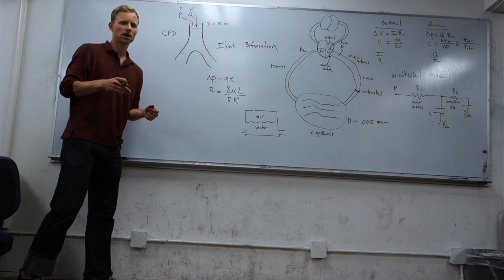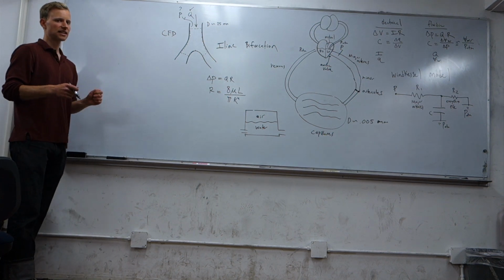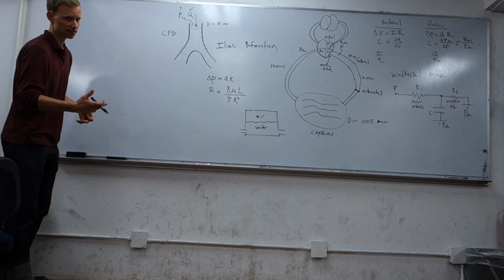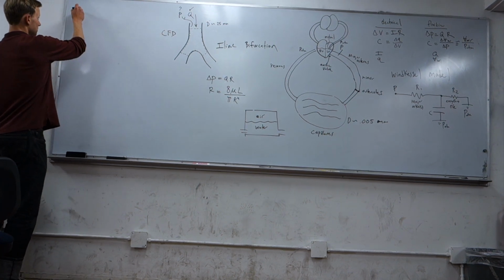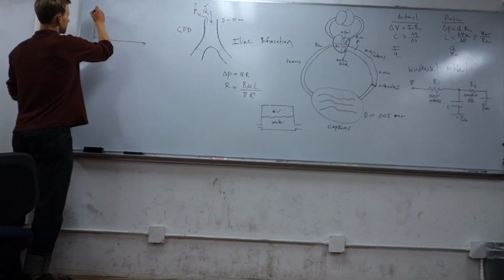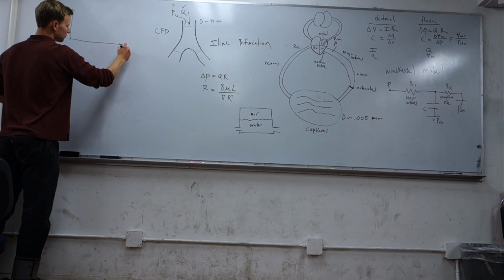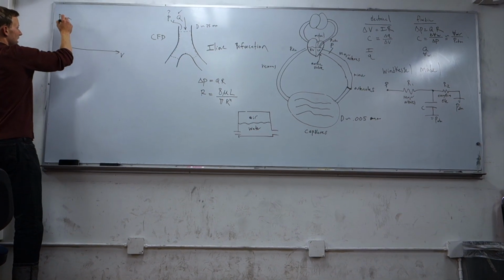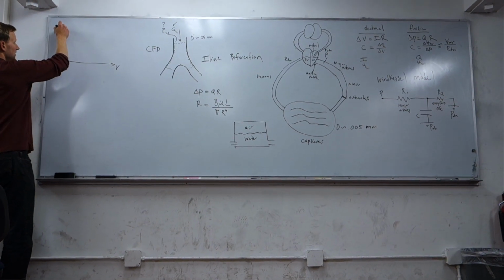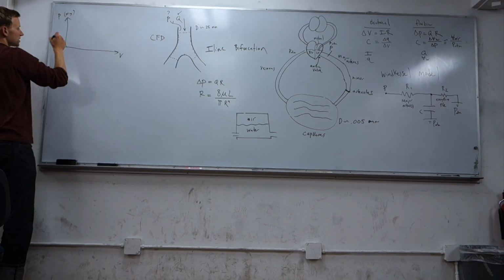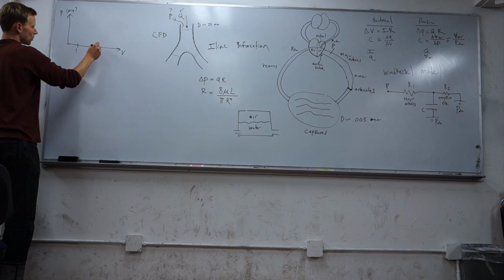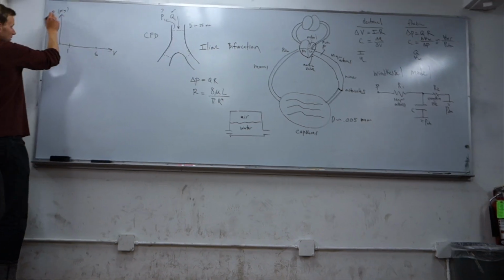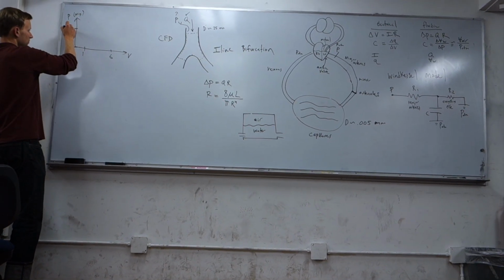This is an important concept to understand: sensors output voltage in this case, and we want a physical quantity. So we have voltage, we have pressure. In fact, our sensor is outputting psi, gauge pressure. Our voltage ranges from 1 to 6 volts, and our pressure ranges from 0 to 10 psi.